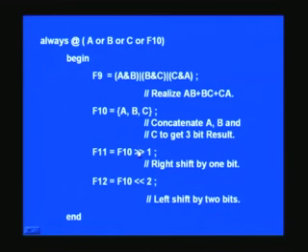We have also seen shift registers, right shift by 1 bit here and 2 bits here. It is as simple as just one statement. After right shifting by 1 bit, it does not affect F10 itself, which is the source. You can make it affect some other signal, say in this case I have named it F11, and that is the beauty of this statement.